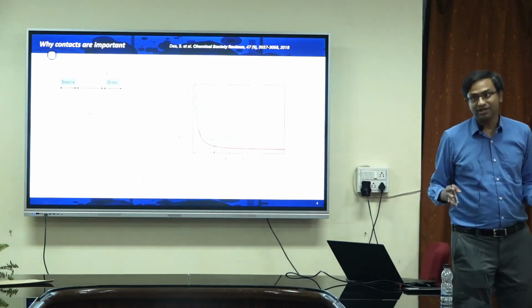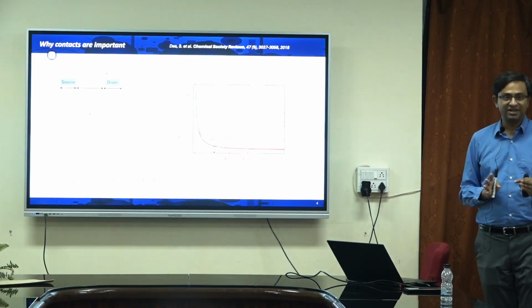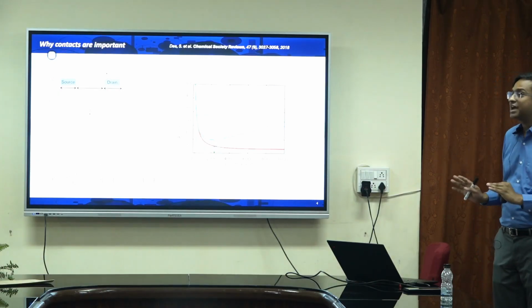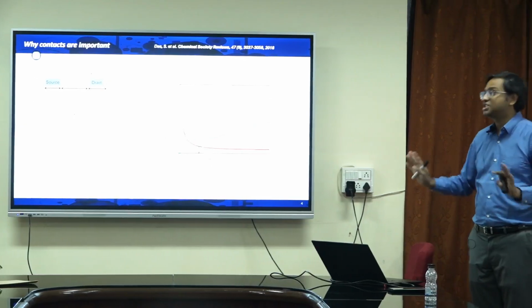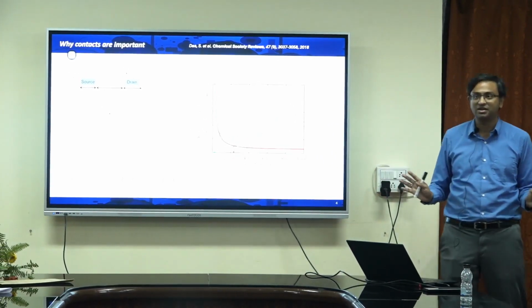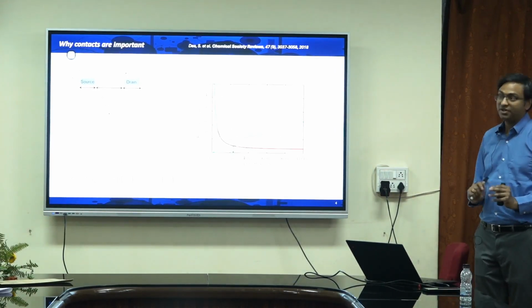So, you see the importance of reducing or understanding the contact for nanoscale devices. Make sense? This is just to establish that contacts are way more critical than even what channel material. This is true for any channel material. Does not matter with this 2D silicon, right? So, therefore, contacts to any material play an important role for nanoscale devices.